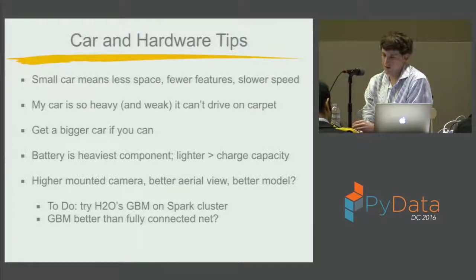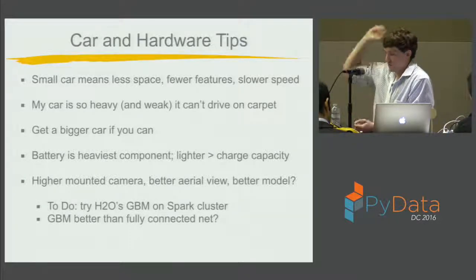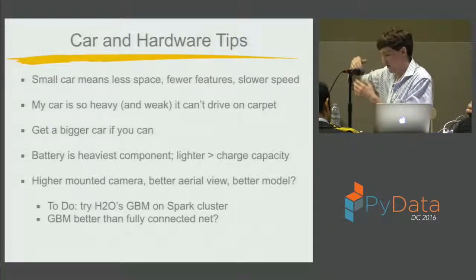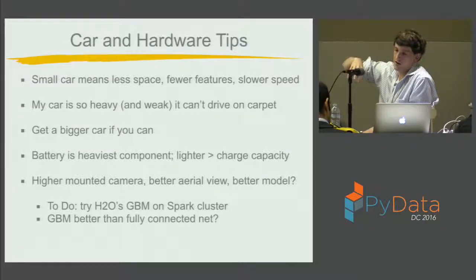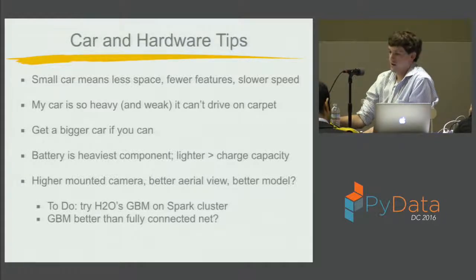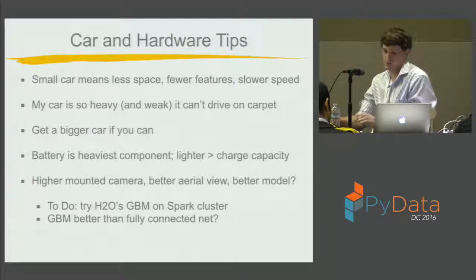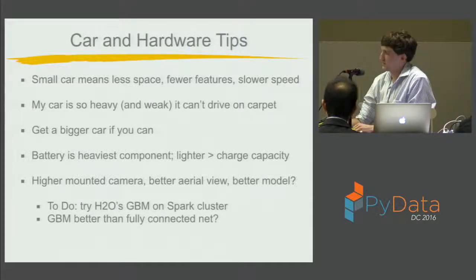Another thing I learned is that the actual real self-driving cars, like Google's, have their cameras mounted really high up. You've got a really good vantage point, and you can see not only the curve that's approaching you, but also where your car is right now on the curve. I went for aesthetics over function, unfortunately, and my car has some glaring blind spots in the very beginning. So if I'm close to an edge, my car might not realize that, and it can overcorrect sometimes. But if I designed this a little bit better, maybe I would have had a better aerial view. So that's something to keep in mind.